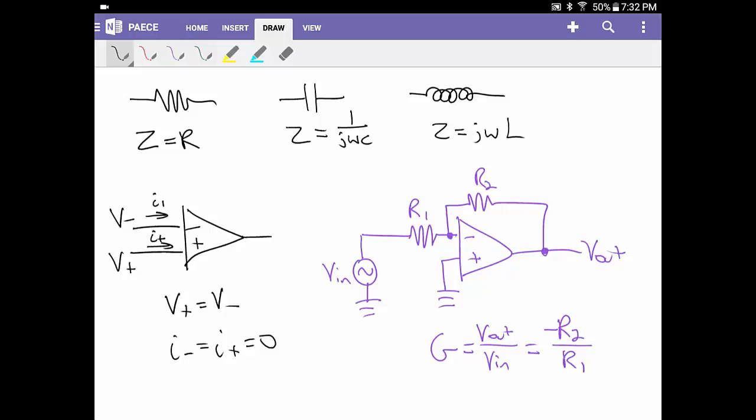The other theory that you need is the op-amp theory. So just a brief recap of op-amps. An op-amp is a 3-terminal device that has 2 input terminals and an output terminal. The 2 input terminals are normally denoted as V- and V+. And one of the 2 rules which really govern the operation of an ideal and perfect operational amplifier is that V+ has to be equal to V-.